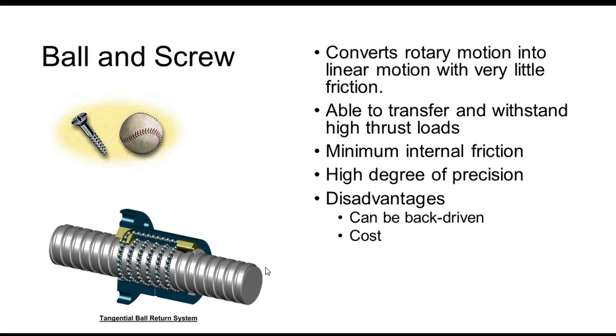When the screw turns, these bearings just follow the groove in the screw, and then they just constantly rotate. So it comes out this side and just runs back around and falls right back down into the screw. So the balls are constantly rotating through the actual unit. The linear motion, I would attach to this, I don't even know what it's called. And whatever we want to develop the rotary motion, we would connect that to the screw. Right? Okay, guys.